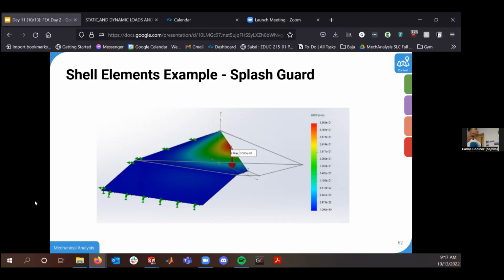Looking back on how I would do this, and I highly recommend you guys do this, when you look at your earlier FEA studies and think about, man, I now know so much more stuff, how would I do this better? I would do this as a dynamic study. In the actual case of tech inspection, it doesn't matter because that's a pure static case. But with the car driving and moving around and having a bunch of highly dynamic loads, I would consider doing a dynamic case and still seeing, will this get to a point, or even looking into a buckling case like this to see if it can buckle and go down. But that's another example of shell elements. We've been talking for way too long.